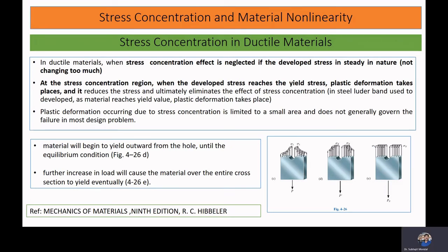How a ductile material behaves under stress concentration, and how a brittle material behaves under stress concentration. If you see a ductile material with some stress concentration, you will observe that the effect of stress concentration is neglected in the case of a ductile material.